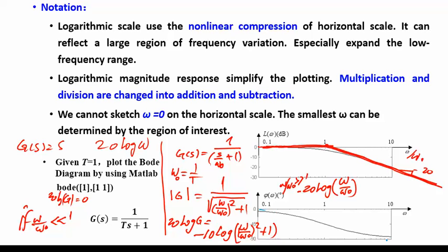If I go here and come to this, I draw one line, 1 decade less, 1 decade higher. You see, I'm not making much error, right? The line should go to minus 45 degrees at the frequency ratio of 1. You don't make much error.